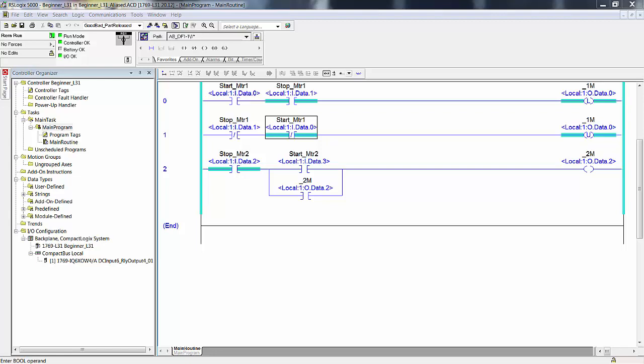This does not actually start and stop the conveyors directly, just enables or disables their ability to start. Following a system stop, we do not want the conveyors to be running with a subsequent system start, regardless of their state when the system stop occurred.